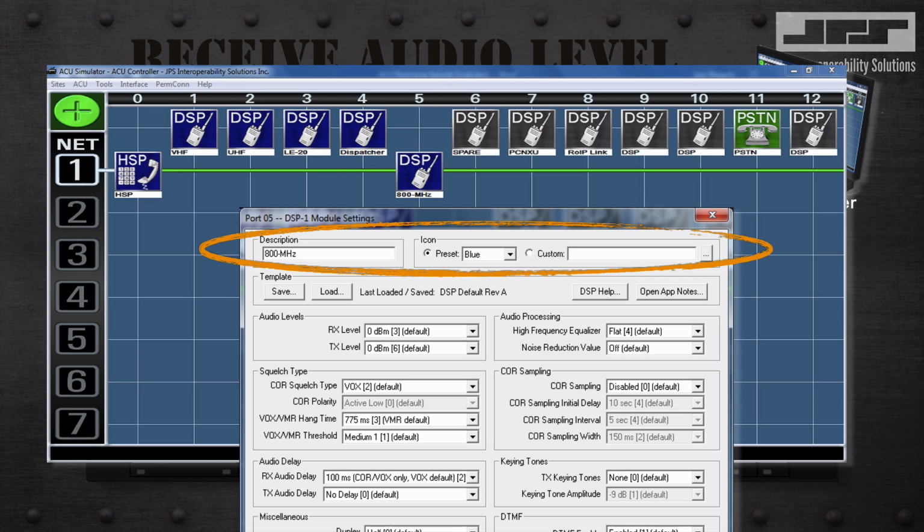For instance, you can also enter a telephone number, just in case you need to call someone to replace a battery in a portable donor radio. You can also change or customize the on-screen module icon. You can also load the appropriate radio template or immediately begin the alignment. I sometimes prefer not to use templates as it helps me better understand the alignment, and it also forces me to address each of the settings to achieve better performing interfaces.